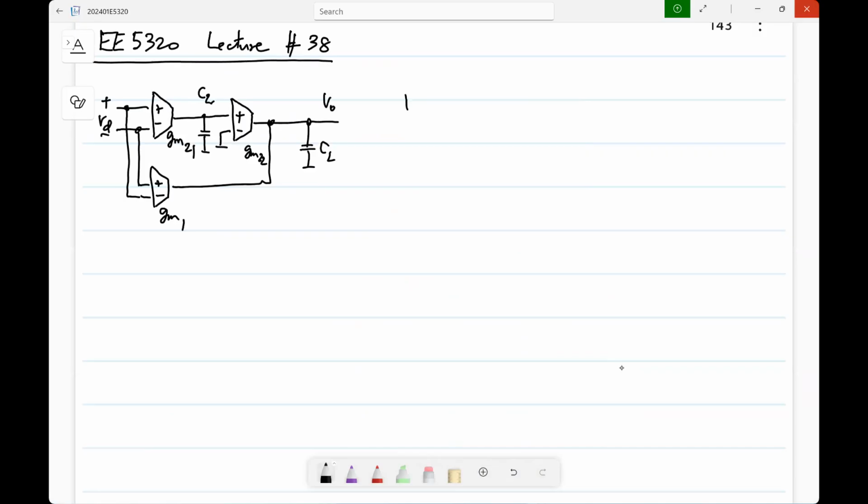So with this, what will be the form of the transfer function? Let's say we ignore the load conductances just for writing a simplified expression. What is the form of the transfer function? What did we get? So basically, you will get something of this form. You will have something of the form of 1 by s square. That's because of the cascade of these two. And this alone will give you omega u by s. Basically, around omega u, it is this part that is active.